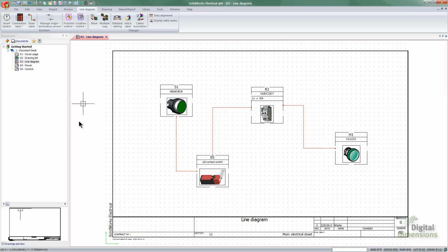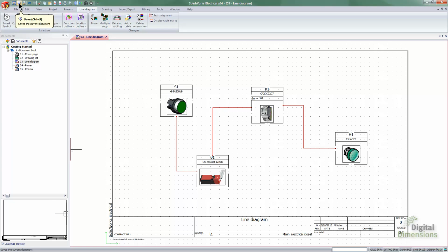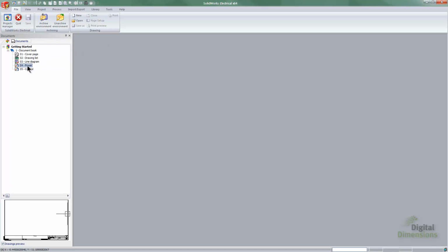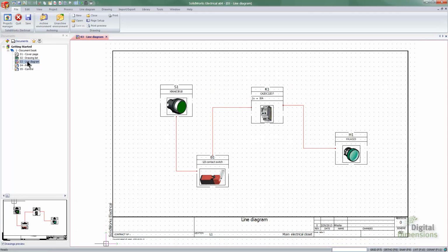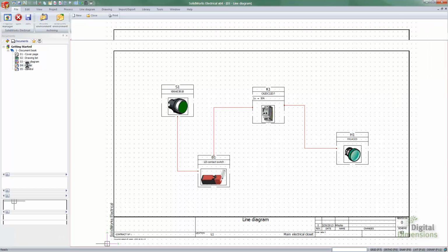Multi-line allows us to go through and get the specific information in there. Oh, you might have noticed that the preview isn't showing up. Well, I can either save the document, or SolidWorks Electrical also automatically stores all the information. So if I close out of the single line and then come back to the single line, you'll see that the preview updates. So you don't necessarily need to save the document. It automatically saves for you. Double click on it and you'll be able to see the full drawing there again. So we'll leave that open for the time being here.